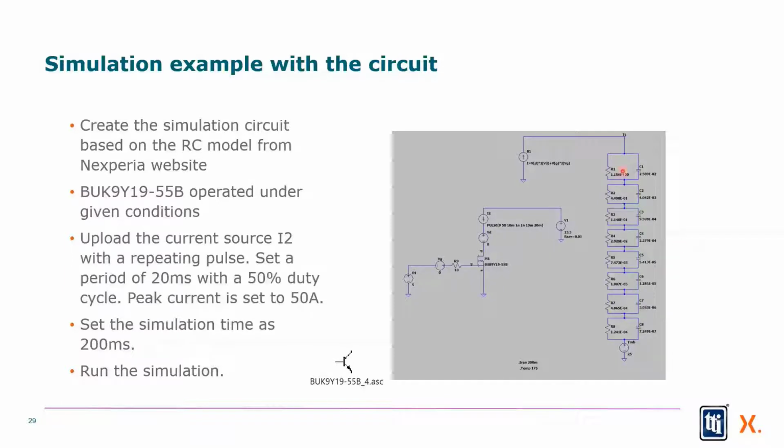And here it is. So this is my input current. This is my starting voltage. This is the RC that I've created from it. And then this is actually the wave shape of the part itself so I can test various parts inside the simulation. This is a SPICE model. I'm not measuring the actual analog response to it. This is a voltage simulation of a thermal model using SPICE instead. So let's see what happens.